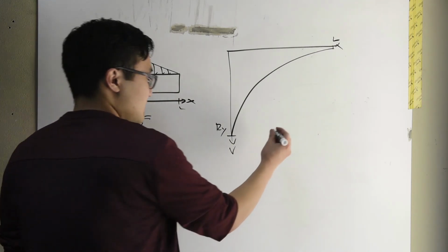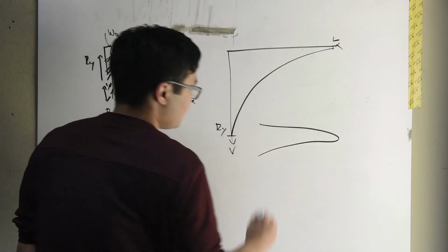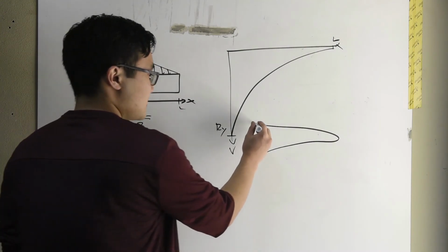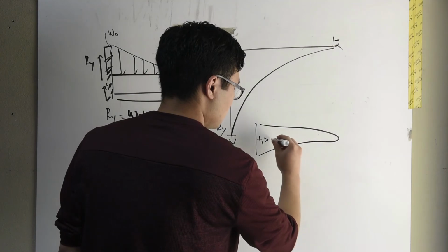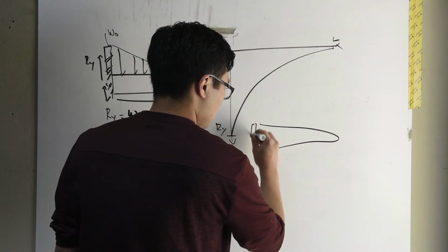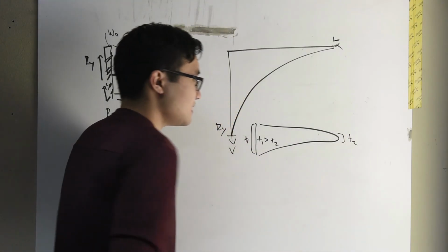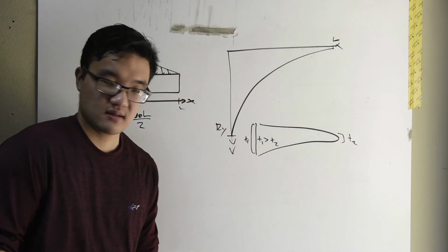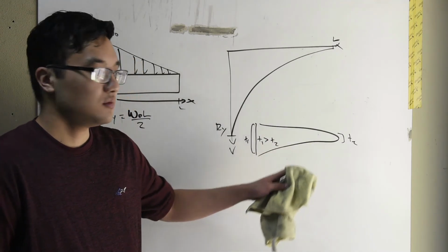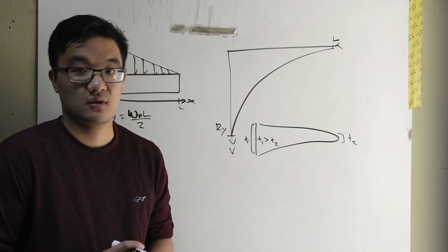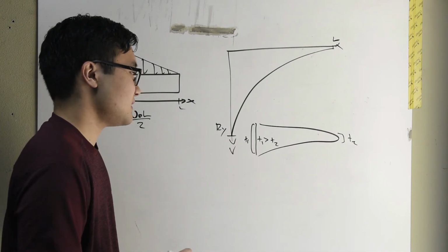That allows us to design for a wing where if I take a side profile, it might look like that, where it's thicker here at T1 than it is here at T2 because we don't need that added thickness at T2. We don't need that additional strength at T2 because that's not supporting as much of the load. So it allows you to make key observations like that, and that's how we decide.